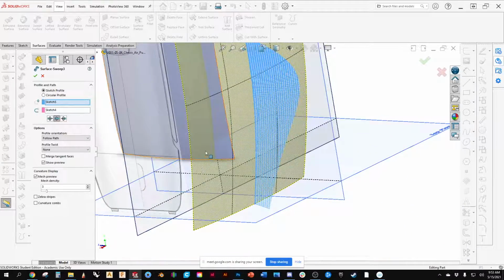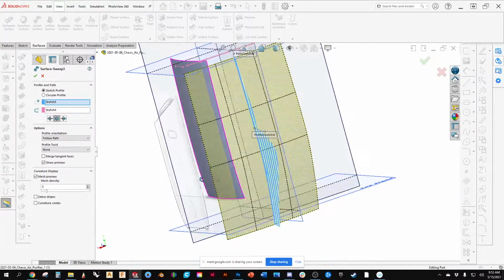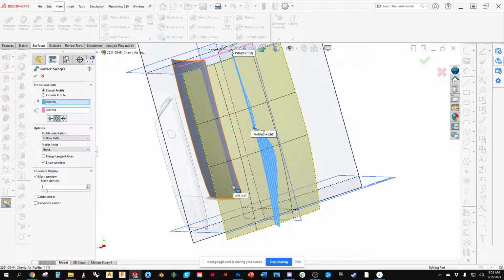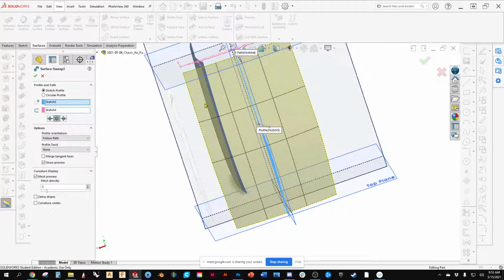It's a nice, clean, simple surface. My isoparms are somewhat equal geometry, left and right, and that's what you want when you can, that your isoparms are evenly distributed. That's helping to show the mathematical structure of that surface, and that it is in its best situation to be a clean surface.